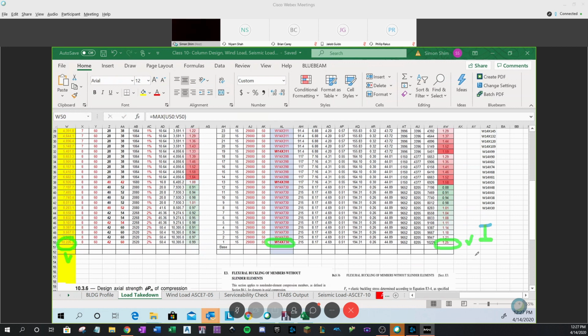So typically, after this, if you want to keep going, there are two choices. If you want to use a rolled section, the heaviest section you can procure is, let's say, the W14x730. We could use the W14x730 and then additionally put a steel plate on each side. So in this case we have to increase the area, but how do we do it?